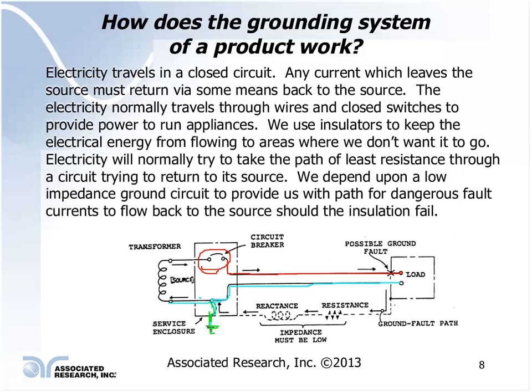So they will allow a certain amount of overload for a given period of time. I looked at some of the specs on some of these breakers, and they can allow up to a 200% overload for up to 2 minutes and still be within specification. So if you have a 15 or a 20 amp breaker, it can carry 30 amps of current for 2 minutes, or 40 amps of current for 2 minutes, and still be within spec.